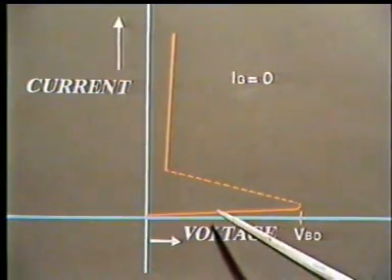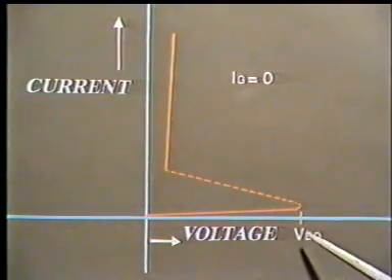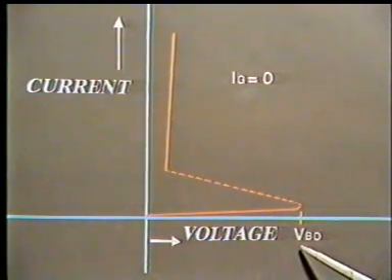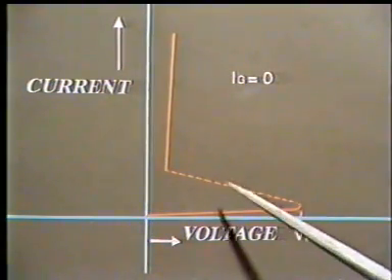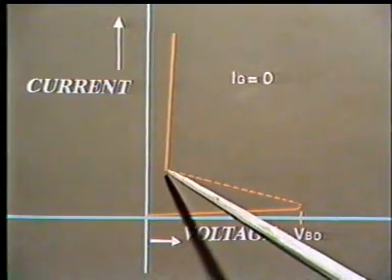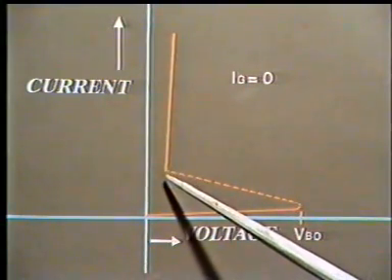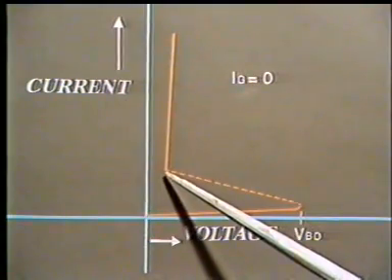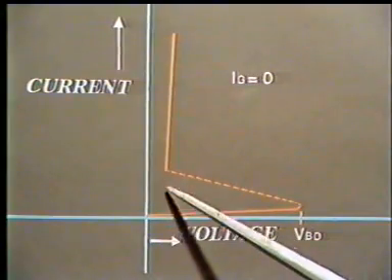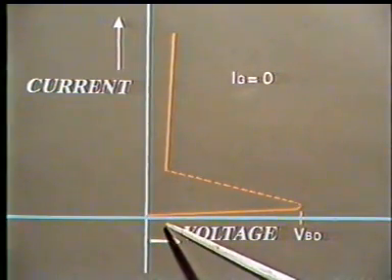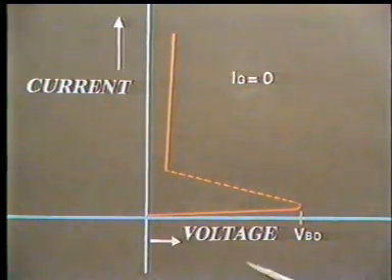As long as the anode voltage is less than the breakover voltage, the current is very small. When anode voltage becomes equal to breakover voltage, the anode current increases and the anode voltage falls. Subsequent increase in supply voltage causes the anode current to increase, whereas the voltage across the device remains almost constant. I hope that with these explanations, the turning on behavior of the SCR must be clear by now.